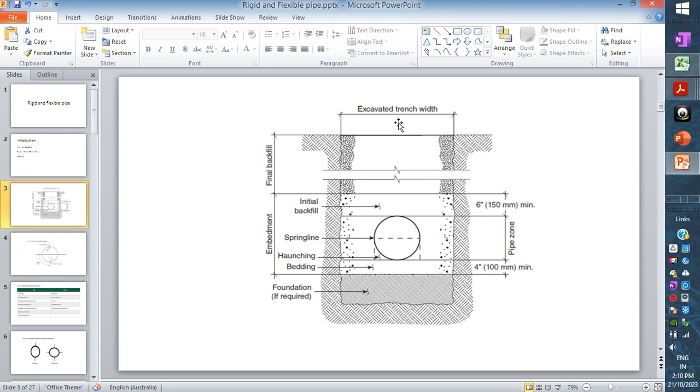We are going to calculate the theory, once you have the embankment in place, for highway loading as well as loading criteria: how much load the pipe will take in a given condition of trench width, height of cover, type of pipe, bedding type, and given embankment condition.